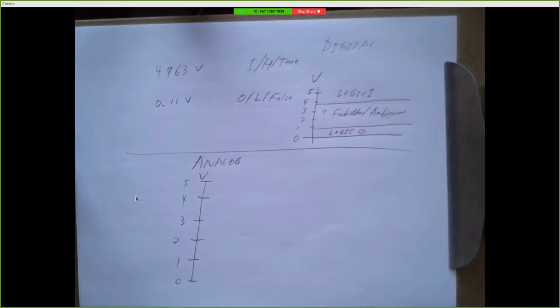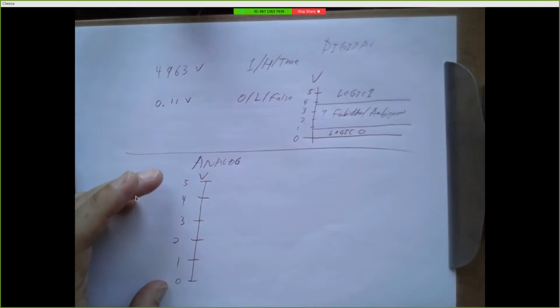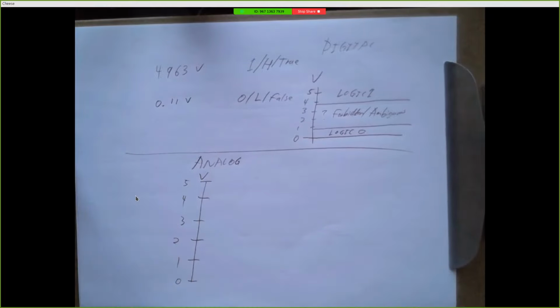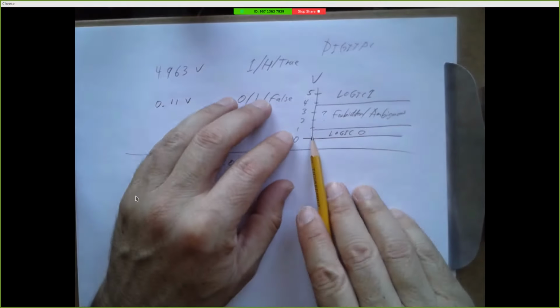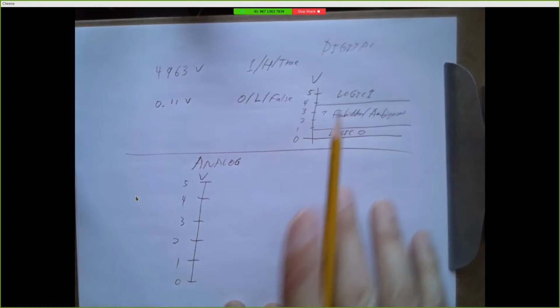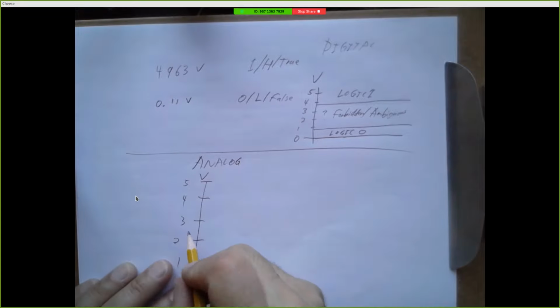We can think of an input voltage range, and typically it'll be 0 to 5 volts because our PIC is powered with 0 and 5 volts. So anything in this range is imaginable. So what we're going to do is we're going to assign a number of binary values to each possible voltage. Because what are we doing up here? We're basically saying if your voltage is here, that's a logic 0. If your voltage is here, it's a logic 1. Well, there's a forbidden zone in the middle, but you know, in practice,